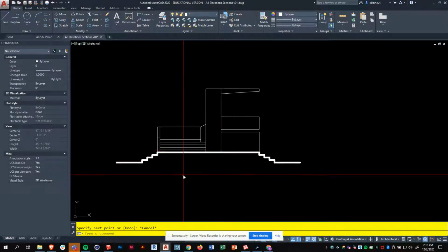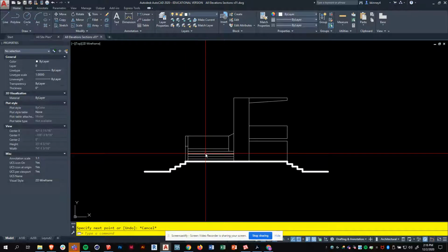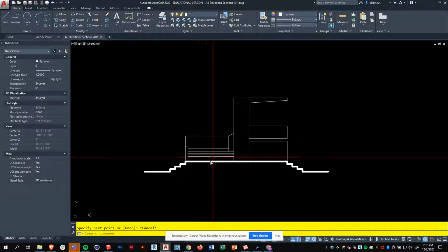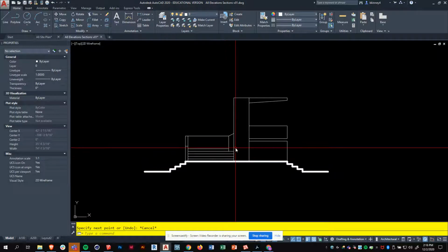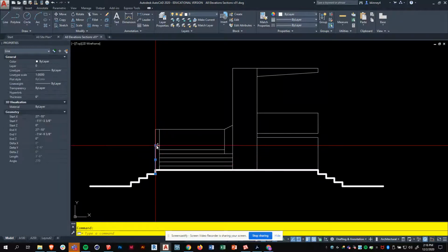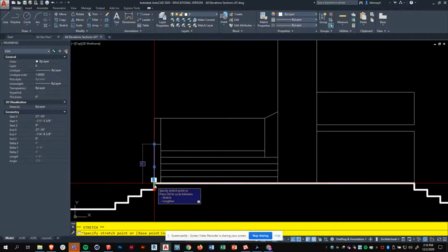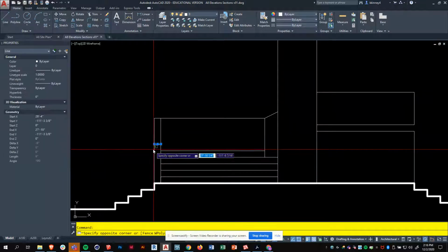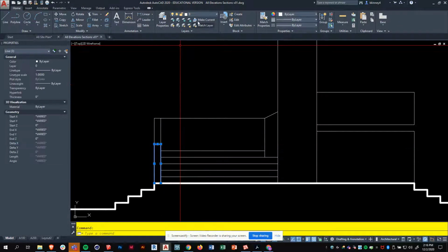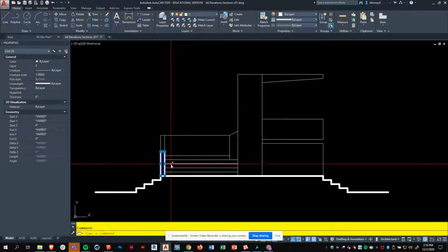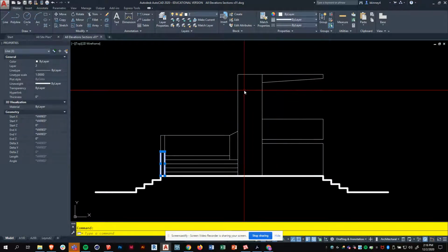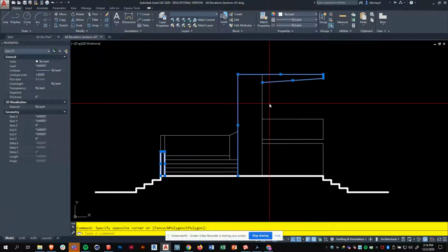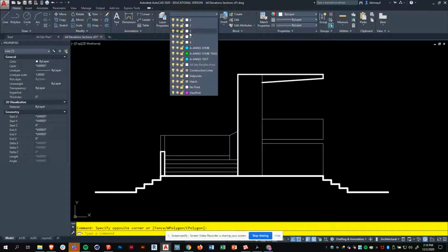So there's one last thing I want to do to this. Well, two. First is I want to make sure my line weights are reading properly. So what I would do is change this one, because this one's close to us right here. So I'll put that at 2. And I will put the outline of this at 2.